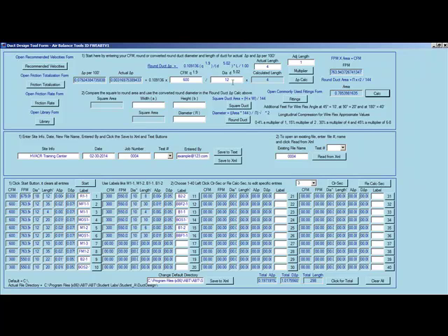If we wanted to change this to a different duct diameter because of our friction loss per 100 feet, say we wanted to change that to a 10, we would see our change, and then we can add it to our section. We could also clear out that one particular section if we weren't going to use it.